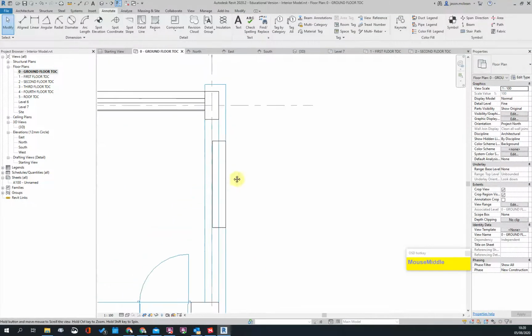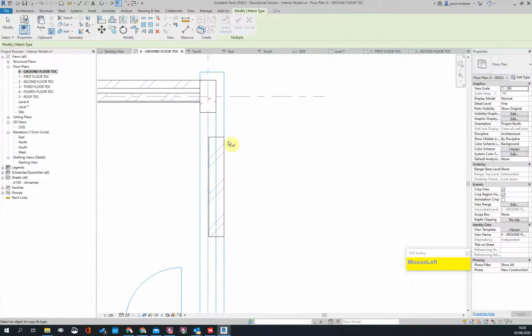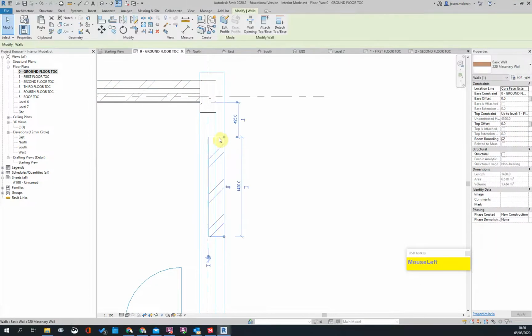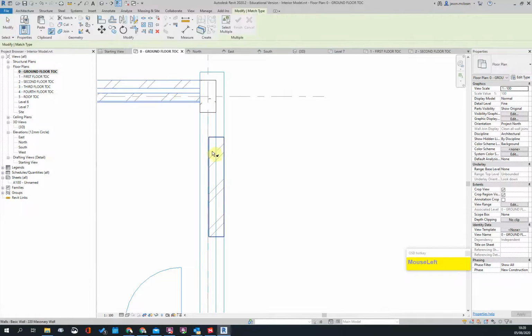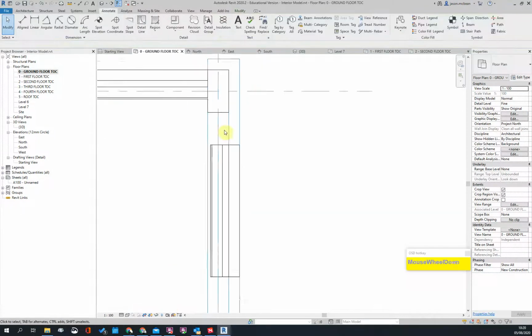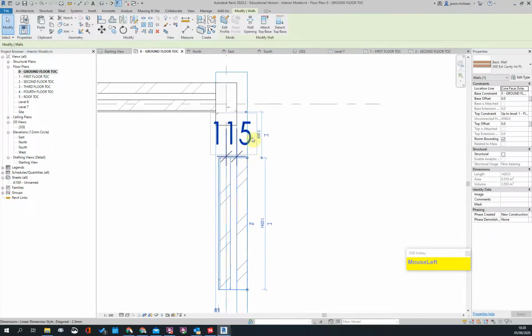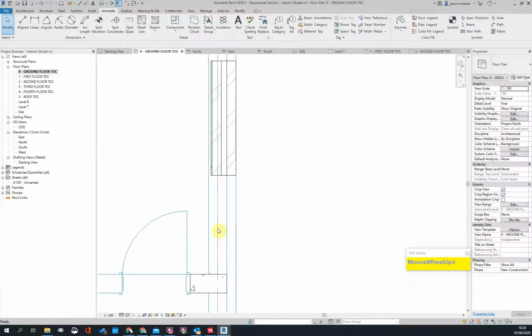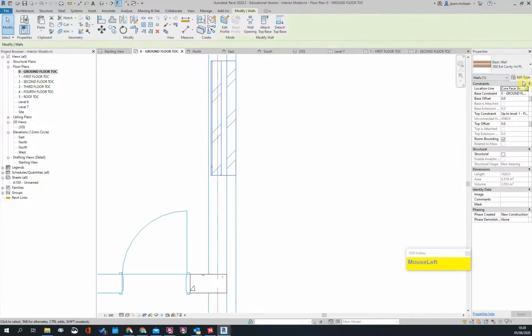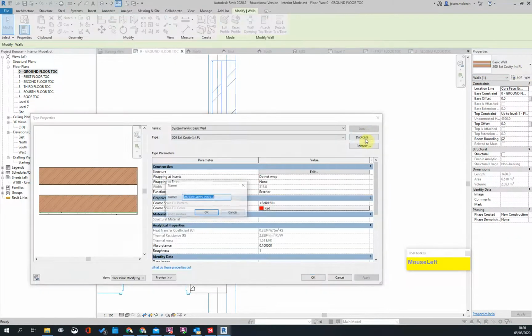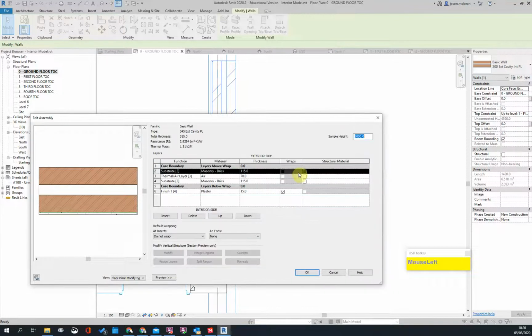Okay, Revit. I'm going to duplicate this wall. I've put a wall down here, so I'm going to use the match key to match that with that. But this cavity is slightly different. You have a much bigger cavity here. The cavity is 115. So I'm going to say it's a 345 cavity wall, DI. I'm going to say edit type, duplicate. This is a 345, plastered. I'm just changing it to PL because it's going to be plastered internally and externally.